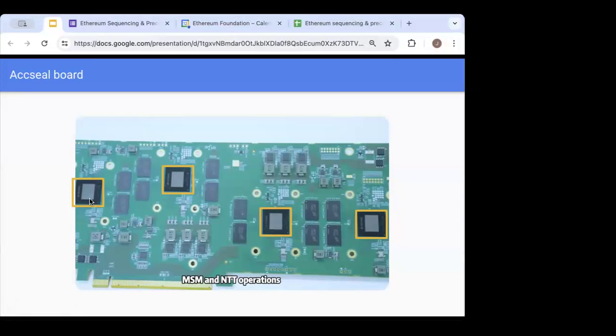Yeah, that's one way to do it, but it's not the optimal way. For the next generation chip, we are considering another way, because we allow chip-to-chip communication. So we can have two chips that each support 64 gigabytes of memory, and then we can let them communicate with each other, and then we can do a very large NTT together, and we can also store the data, the first half in one chip and the second half in another chip. Yeah, but that's for next generation.